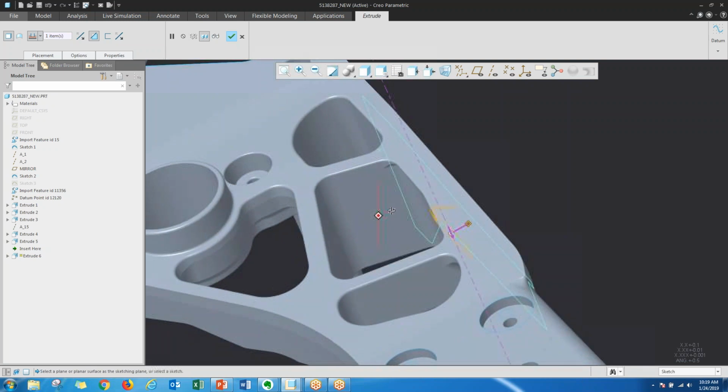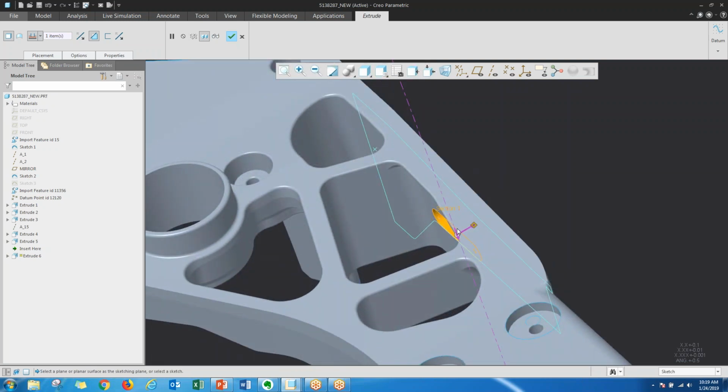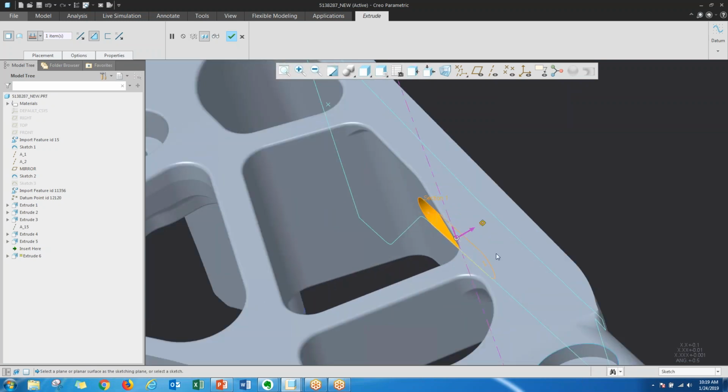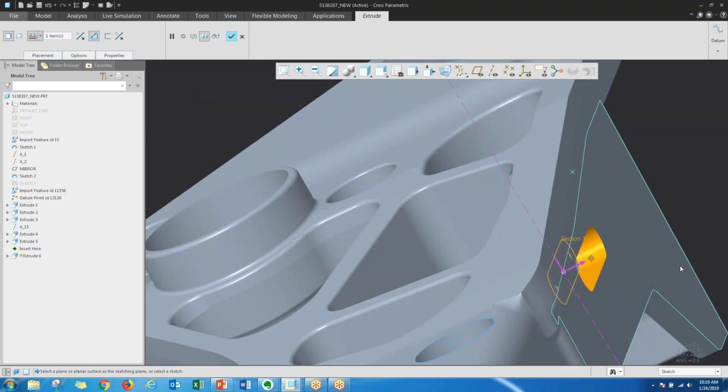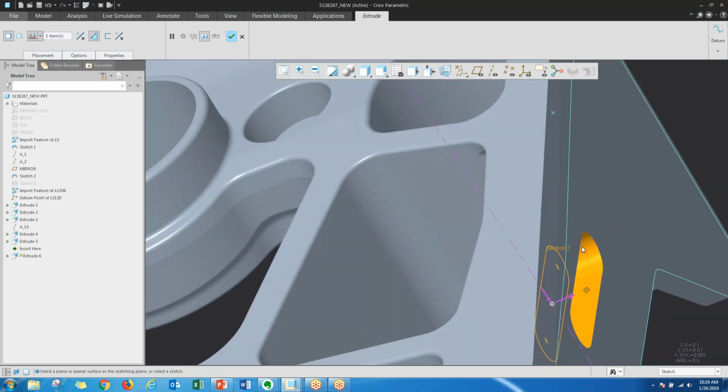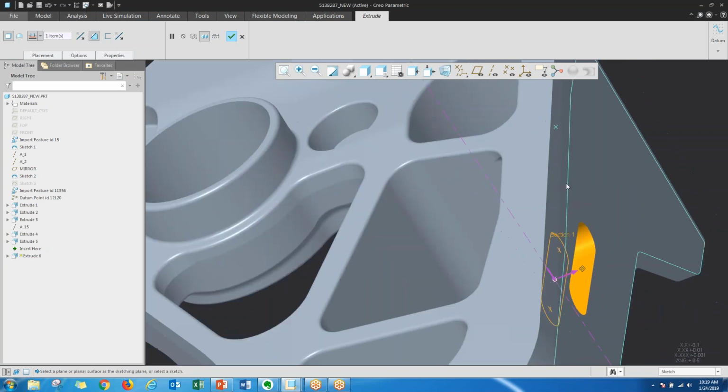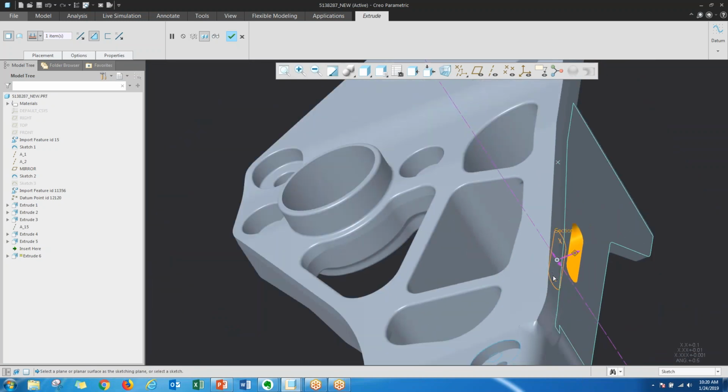Now, there may be a case that I need to actually extrude this to a certain depth. Let's say not all the way through, but I wanted it to be offset 2 units away from the back surface instead. Now, typically, what I would need to do is drop in another datum plane in order to use my to selected command. However, included in the to selected depth option, I have what is called offset from surface.